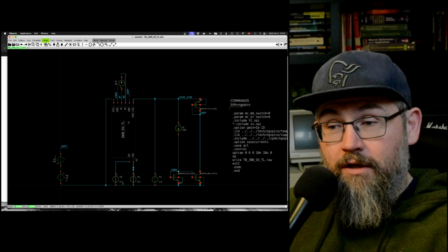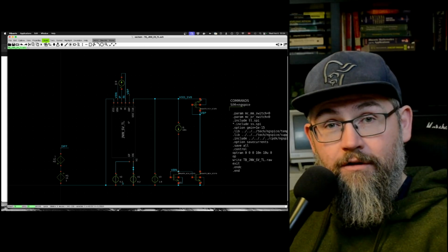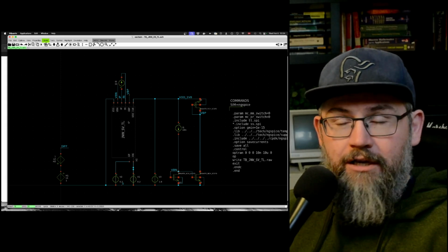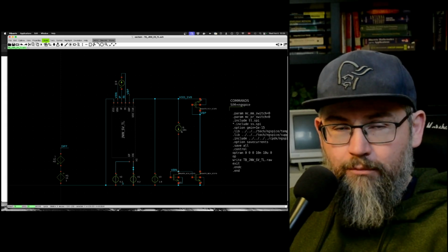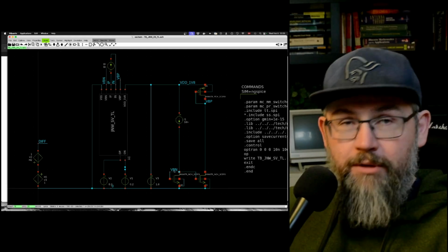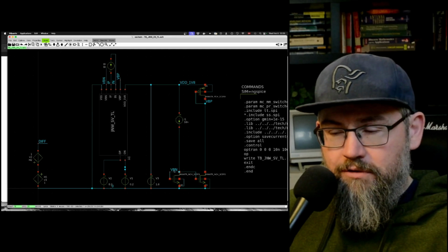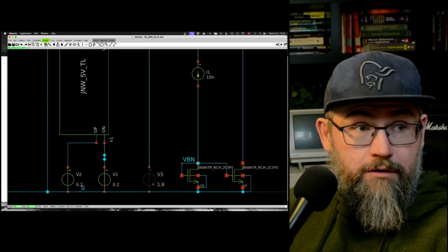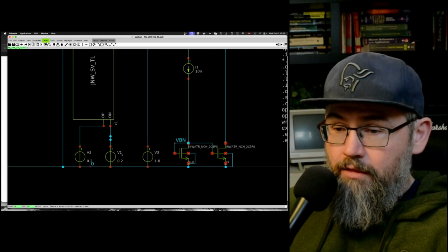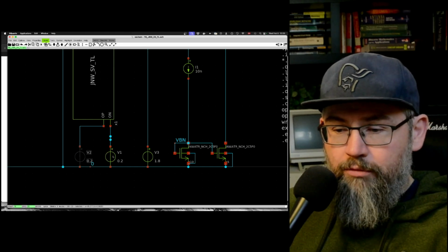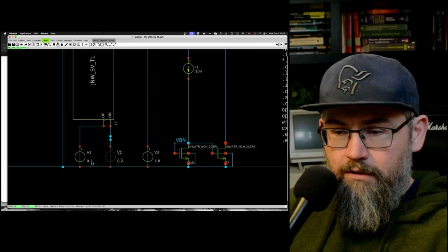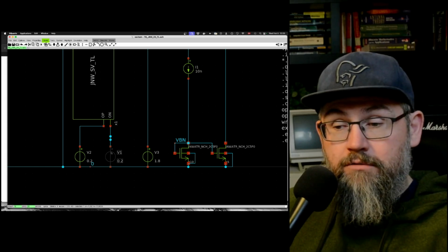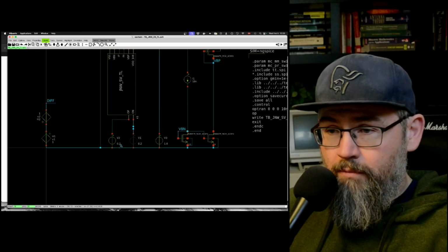I've chosen to put those outside in the test bench because if we're actually going to use the multiply block here in a neural net, then you would need n number of them. And it might be thousands, and you don't want thousand versions of the bias current. It's going to be more inaccurate to distribute voltage across the array, but you probably have to do that. We have a supply voltage that is 1.8 volts, and then I'm forcing the output voltage, the OP and ON, to be 0.2 volts, so I can measure the current in the output.